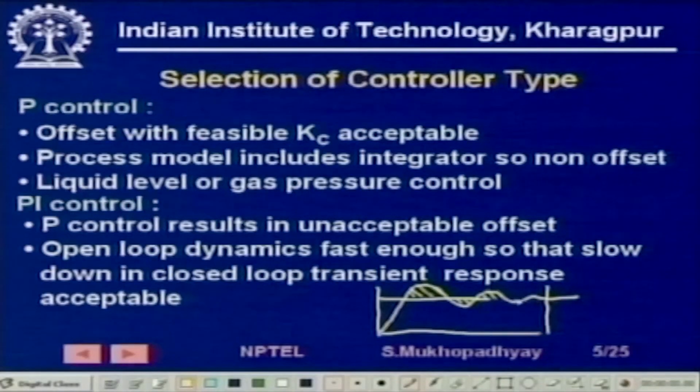Obviously you will find that they are acceptable when, see, every time there is a set point change, such an oscillation will result. It will die down, and from then on the loop will exactly achieve zero steady state error.